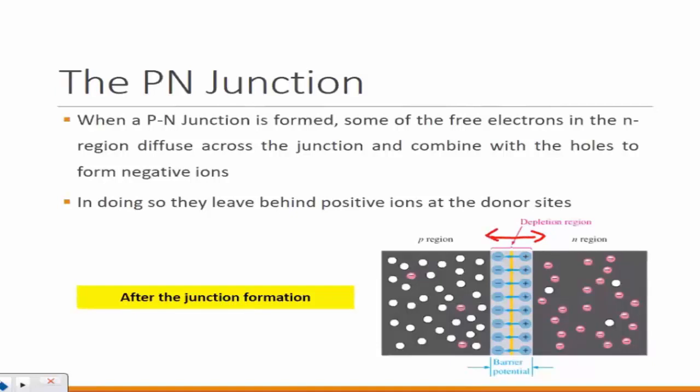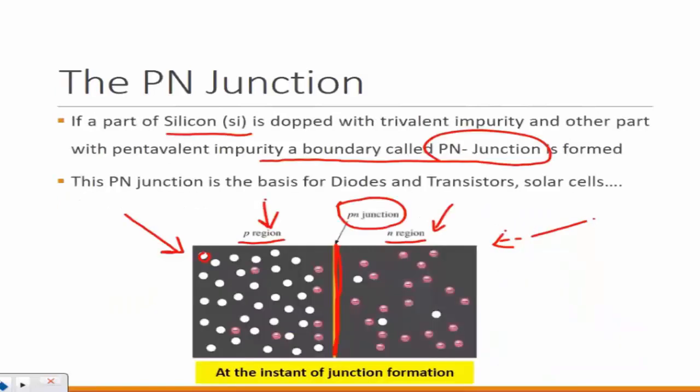So you see that the width of the junction is actually increasing, right? So why is it increasing? Why the width between the separation? What will happen is, remember that you have oppositely charged particles on either side, correct? So now you are putting them together. The electrons near the junction will try to attract and fill the holes on the opposite side, correct? So now a movement of these electrons will occur.